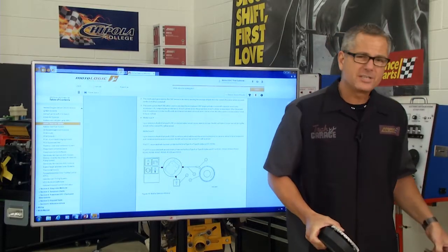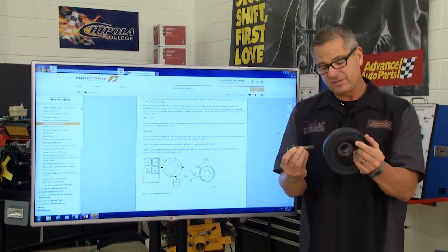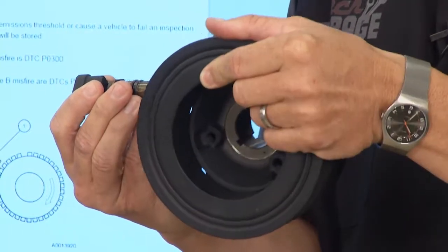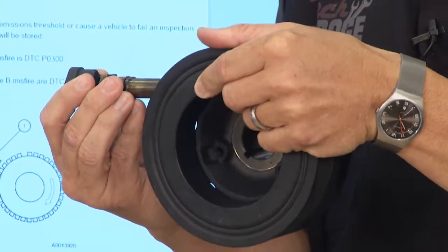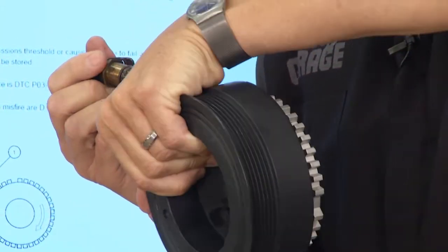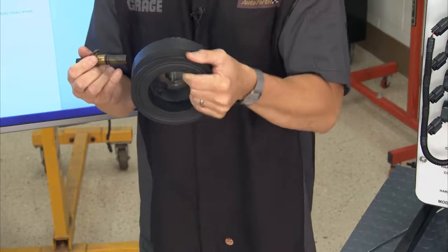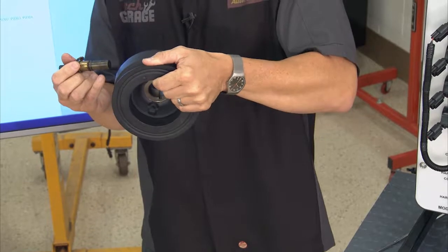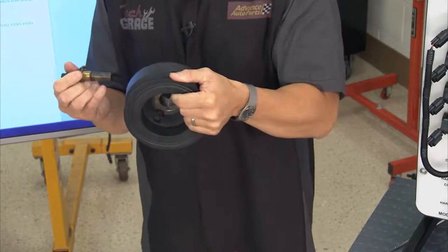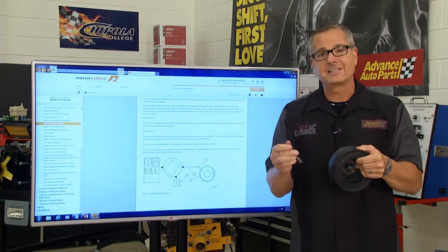I have a good illustration for you, and this is really neat because what's happening is the actual engine fires. Every time the engine fires, the crank has a pulse. So what's happening, I go 1, 8, 6, 1, 8, 6, and it knows everything's all right. But if I went 1 and there was a slow lag, and then 6, it missed that cylinder. And after it sees that, after a given period of time, it kicks that check engine light.